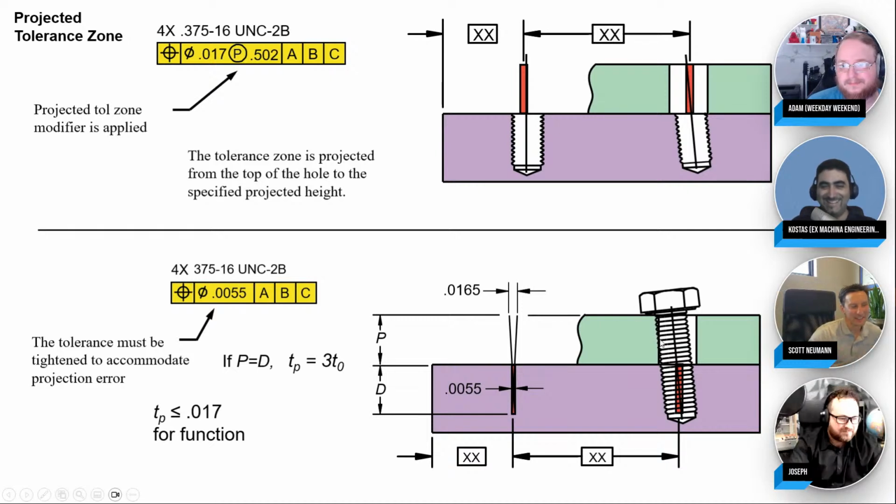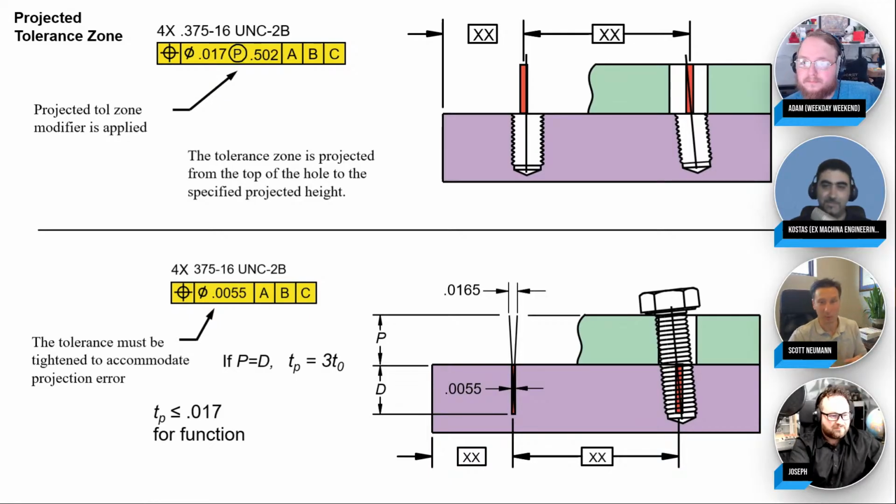Yeah. The thing is, it's just going to cause interference, and really what happens, you put the torque wrench to that thing, it's going in, right? So you're going to end up cross-threading stuff. Cross-threading, shifting the top plate, and then another part doesn't fit, and then another part doesn't fit, and then you're chasing. You think that the problem is with the other part that doesn't fit, where this is where you made the error. It's so much simpler to just think of it and specify it properly.